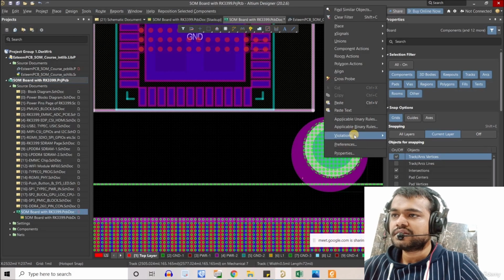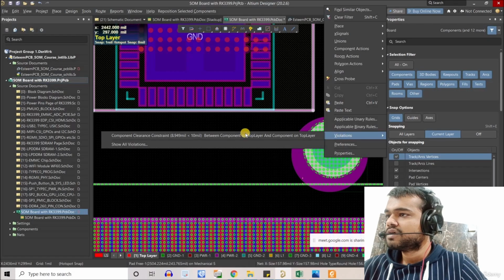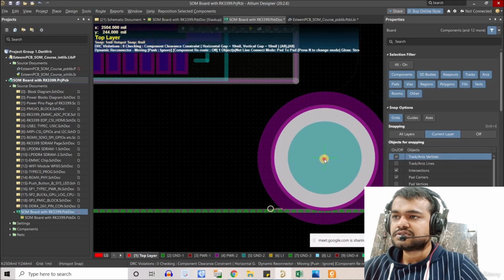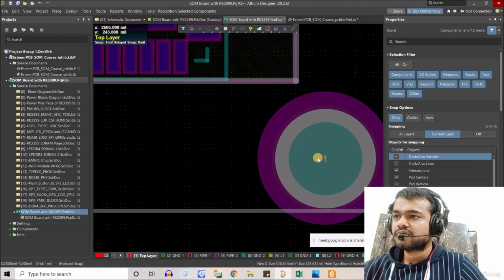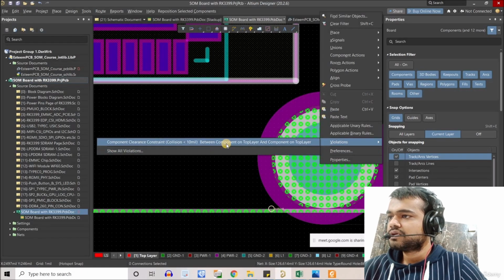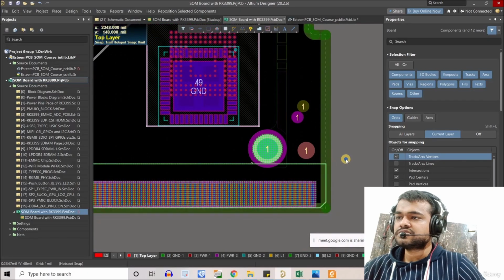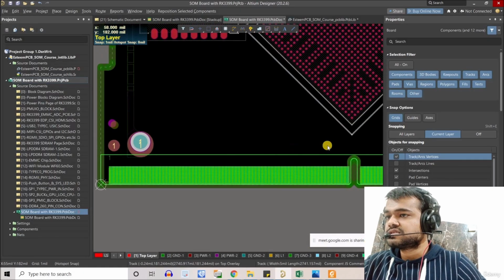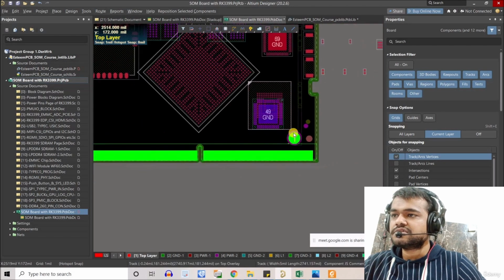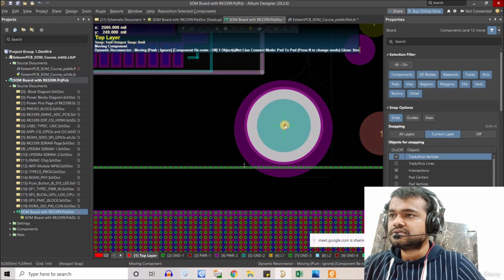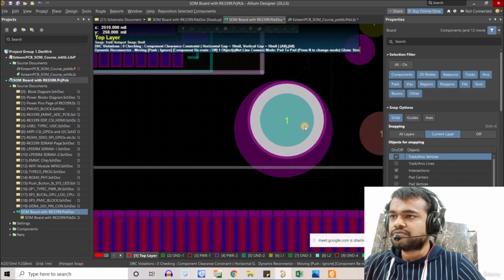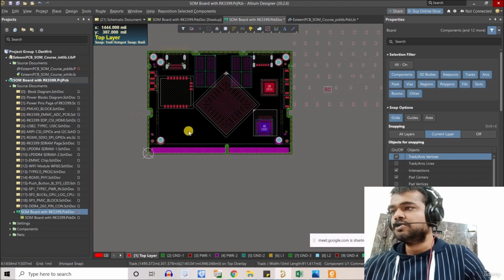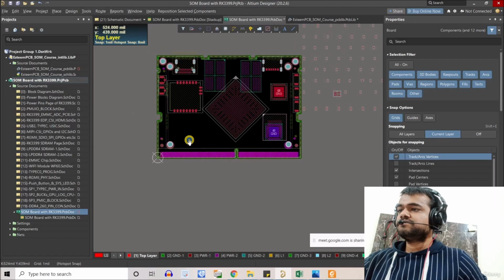Okay, what is the clearance constraint? If you check on the violation, it is defined at 10 mil, right? And if I place it at the center of this, what is the clearance issue? Okay, so it is saying it is a collision. That collision is happening because of this marker, and obviously this part is going inside this DDR4 connector. Okay, so we don't have any option, we just have to adjust this mounting hole, and yeah, that's it.